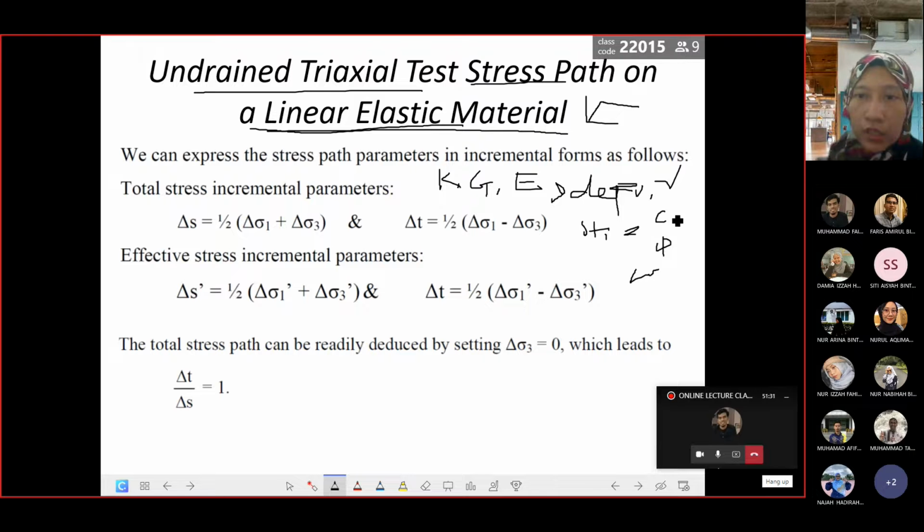For example, the value of CV in unloading and loading conditions, then in undrained or drained conditions. How about the parameters, effective stress or total stress parameters. All those things you have to take note of. If it involves soft soil such as clay, silt, or that part, you have to also consider its consolidation history. Is it NC or is it over consolidated clay, and then what are the values for this kind, if it involves K1, K0, KV and also KH.